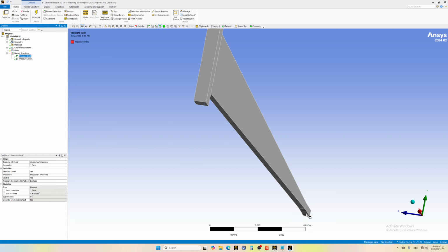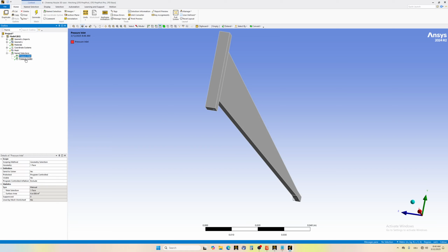So pressure inlet, you see it points where you have the pressure inlet. Check this in case you forgot to select some surface, and here we have 6 faces. Again, it points where you have the pressure outlet. You can define the wall or not, it doesn't really matter. When you import it in Ansys Fluent, it will detect automatically as a wall.